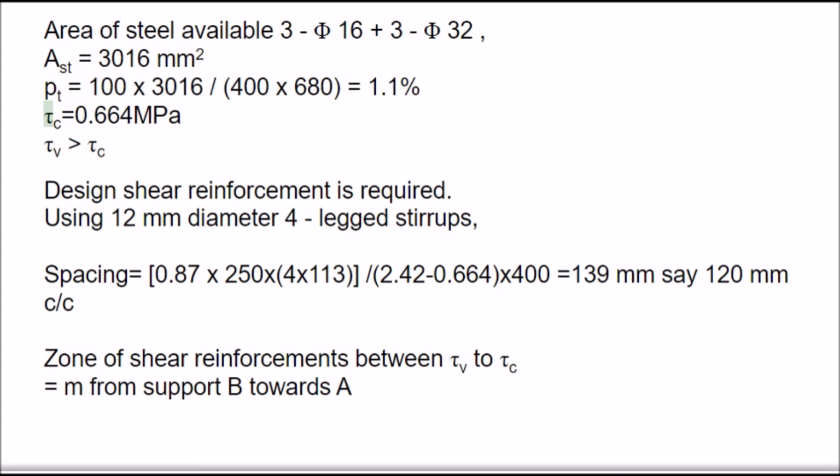Tau c equals 0.664 MPa. Tau v greater than tau c. Design shear reinforcement is required.